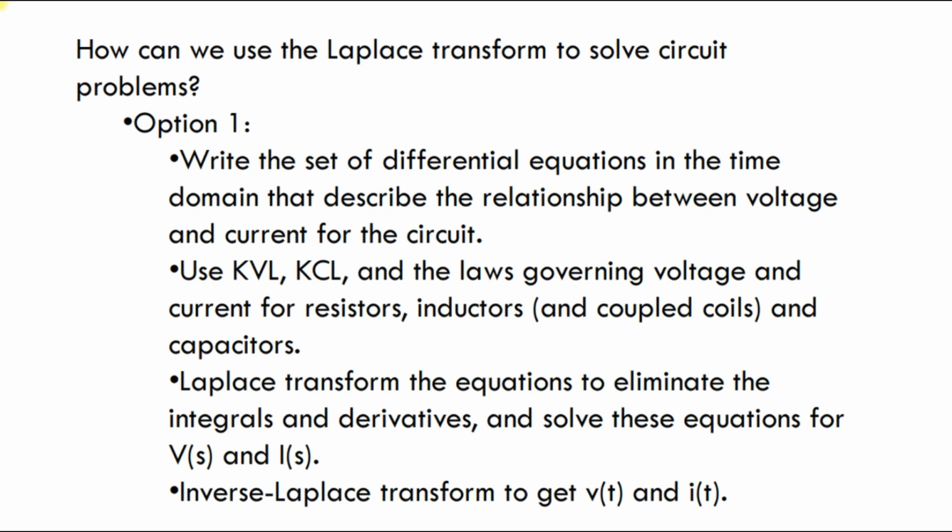The first one is to write the set of differential equations in the time domain, describing the relationship between voltage and current for the circuit. Then you apply KCL, KVL and other laws, for example mesh analysis, node analysis or the superposition theorem. For your understanding, I take KCL and KVL, and if I go for mesh analysis, I write KVL equations for the resistance, inductance and capacitance.